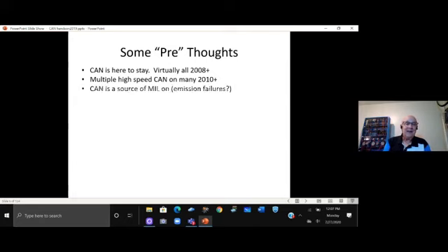Now I don't know where you are, but my guess is some of you are in states that have vehicle emissions, and if your vehicle emissions involve MIL-on or monitors, CAN is a frequent source of MIL-on or of monitors that will not run. So if either one of those 2 scenarios, the MIL is on or the monitors haven't run to completion, any one of those is an emission failure or perhaps a reject or whatever, hey, you have to get into CAN. Okay.